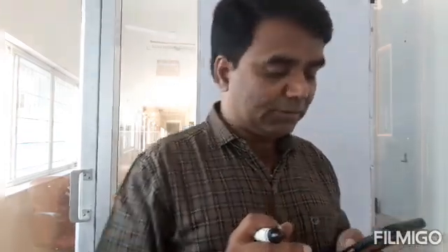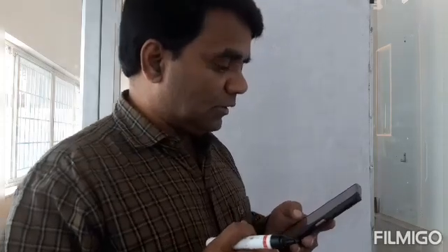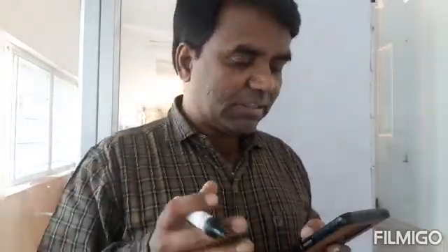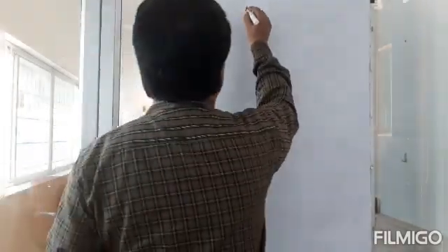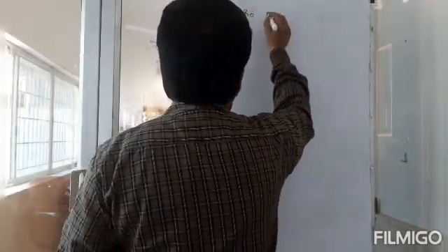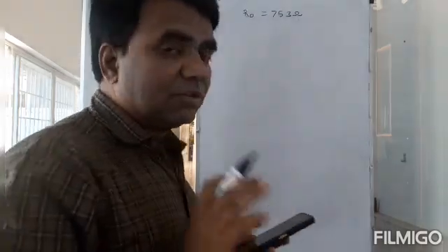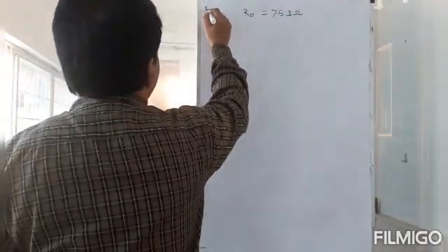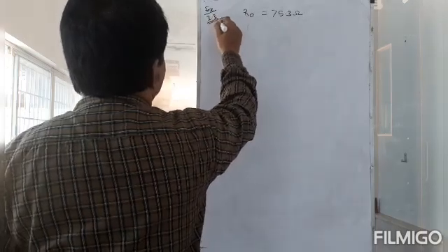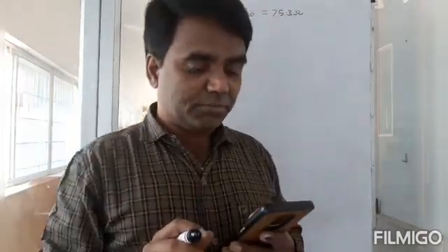So what is happening? First of all, you have an electric toaster that has a heating element. It's a nichrome heating element. When a negligibly small current flows through it, which means it's not going to heat it up, at room temperature the resistance is found to be 75.3 ohms. Let's say R0 at room temperature is 75.3 ohms. That's the resistance of the heating element.